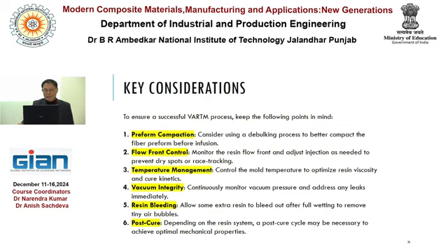That means vacuum pressure is what gives the compaction. The compaction pressure is only atmospheric, 1 atm. So if the vacuum inside is not complete, the compaction pressure will be diminished. So it will be a different situation from what we expect.